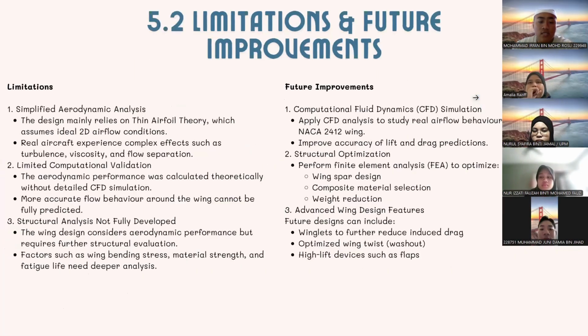So the next one is the limitations and future improvement. So first, the design has several limitations. First, it relies on thin airfoil theory, which assumes ideal two-dimensional airflow and does not account for turbulence, viscosity, or flow separation. Second, the aerodynamic performance is based on theoretical calculation without detailed CFD validation. Finally, while the wing is aerodynamically optimized, further structural analysis is needed to evaluate bending stress, material strength, and long-term fatigue performance. For the future improvement,